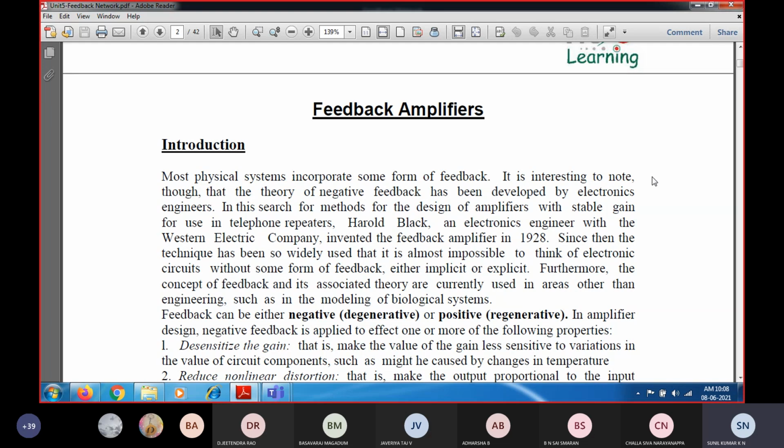In order to find the bandwidth for any amplifier, we can see what the bandwidth is for a corresponding common source or any other type of MOSFET amplifier. We have seen in detail the common source amplifier. There we saw that the amplifier performance was constant in the midband frequency, and over the lower frequency range as well as the higher frequency range, the gain falls off.